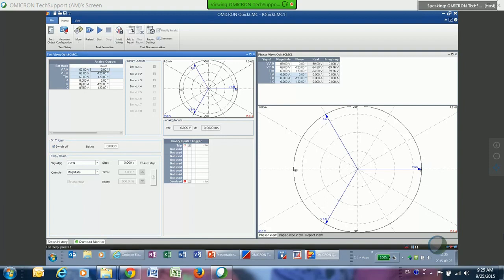Now here again, I could do the same thing with the next cells, but I want to make this more simplified. If I go back in there and do a right click, I can change this to equal magnitudes, and all three of those get filled in to that same value of that cell that I was working with. So let's say, for instance, I wanted to change cell 1 to 50 volts.